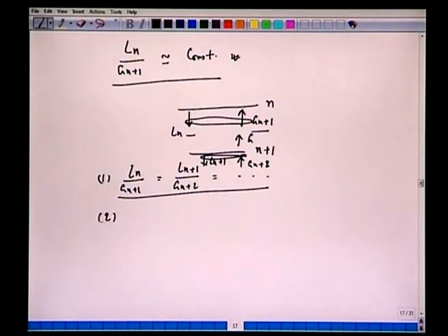Number 2, if you look at any plate, for example plate N plus 1, the molar flow rate of vapor is Gn plus 2 and the liquid which arrives here is Ln, the same as the molar flow rate of the leaving streams, which is Gn plus 1 plus Ln plus 1.